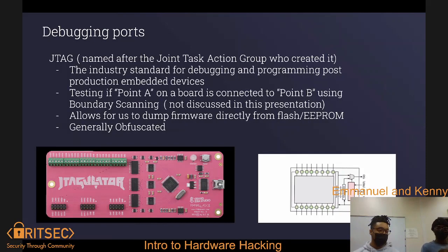Yep. And like I said before, although a lot of engineers enjoy including it on their products, they don't want people opening their products and doing hardware hacking. So they generally obfuscate the pins, normally not labeling them or putting the pinouts in random places all around the board. Someone created this thing called the JTAGulator, which literally just fuzzes the board to find the JTAG ports. I intend on getting one of these and doing a little bit of router hardware hacking eventually, so we may see a presentation next year. Cool stuff. There's a list of tools at the end that would be suggested if you really want to do hardware hacking.